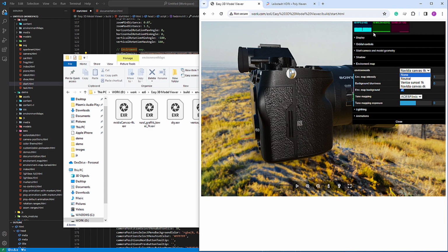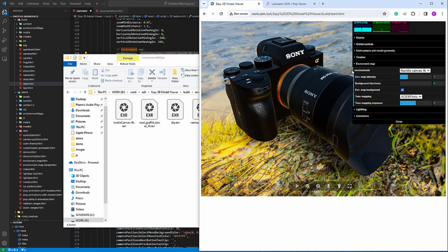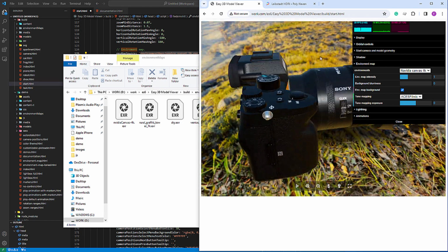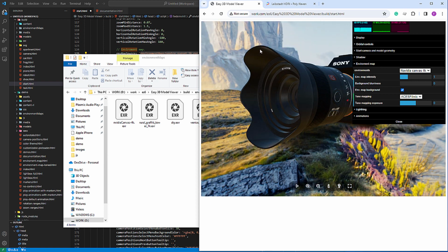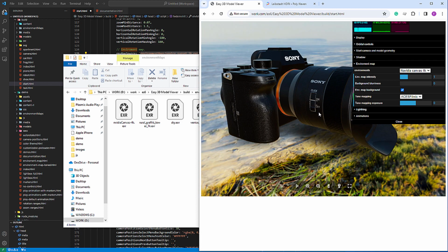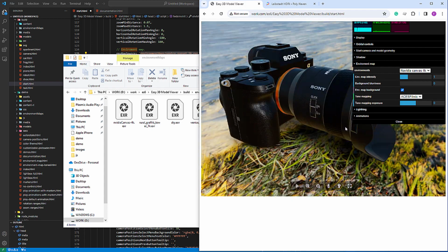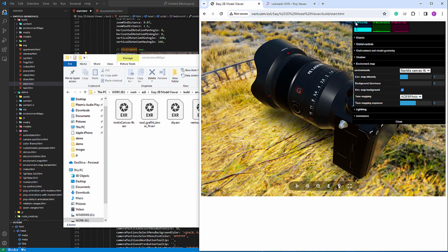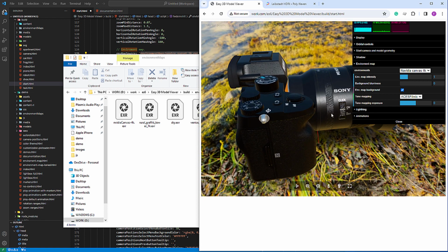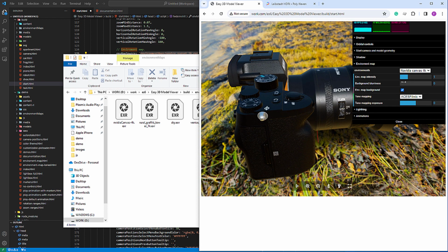And if you see a drop in frame rate, please note that sometimes when using this you'll see a small drop to 56, 55. That is not important, because this tool is not always showing the correct values. I also did some performance improvement tweaks, and it's normal to have these small frame drops. If you see something like 40, 30 frames, then there is a problem and you need to address it. Either improve the model or improve the environment map.